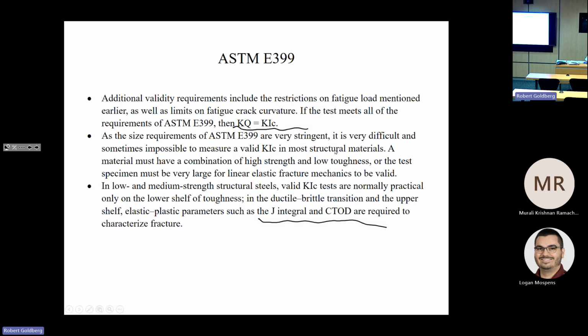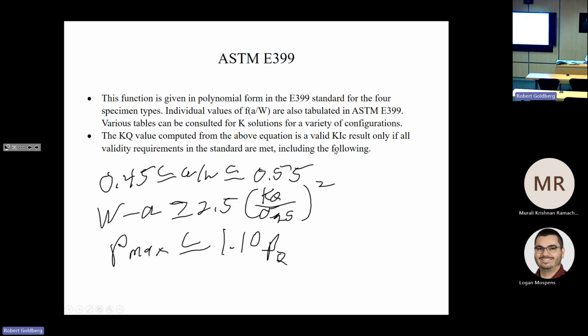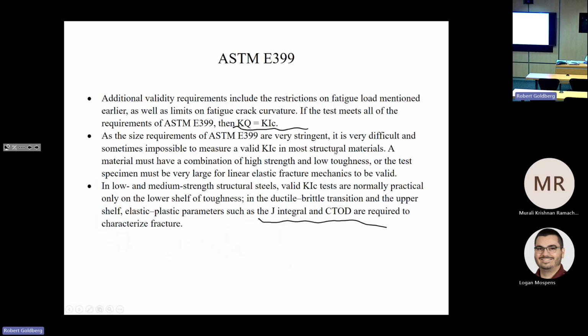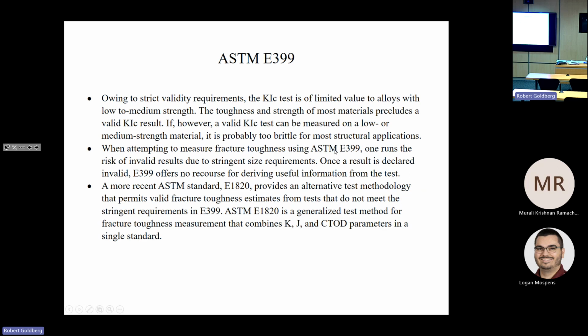So just realize that you have these conditions, and depending on your material, you may or may not have sufficiently linear elastic response, and therefore you may need to incorporate elastic plastic fracture mechanics. So you just have to be careful to see if you fit, or fit close enough, the requirements that indicate you have a valid test.